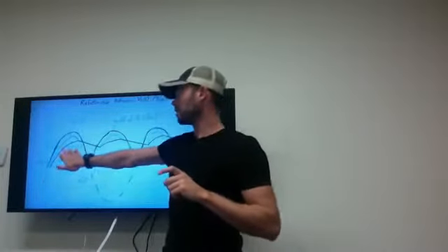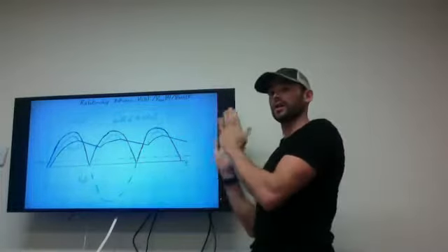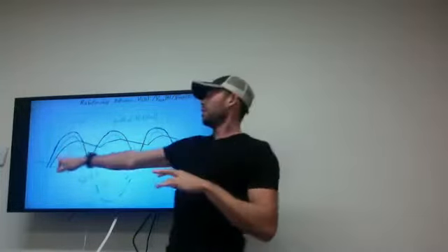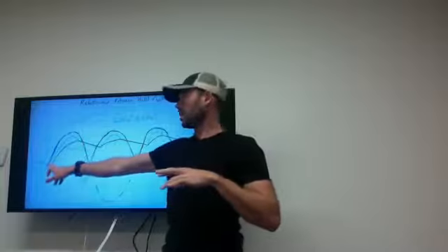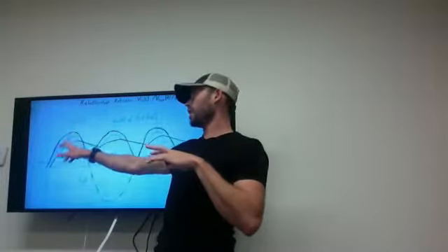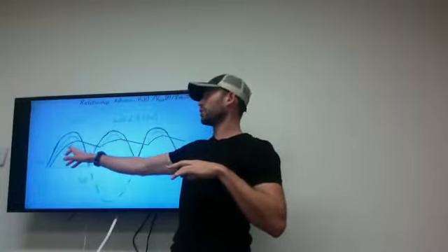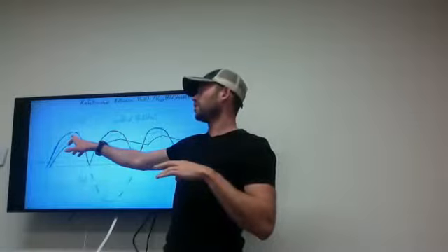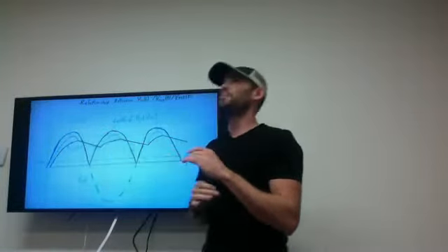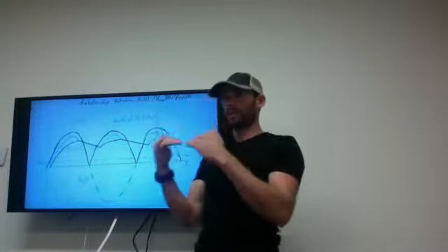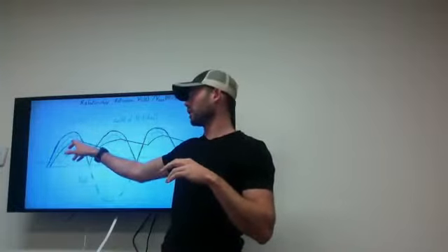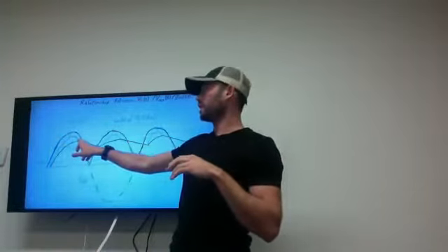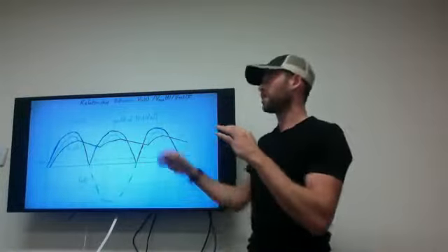This is V out, which is the voltage across the capacitor and the resistor that's in parallel with it. When V rectifier is following the sine wave, V out is still directly proportional to it. But just because V rectifier begins to decrease does not mean that the capacitor is going to discharge, because V rectifier is still greater than V out, until we get to this point, where V rectifier equals V out.